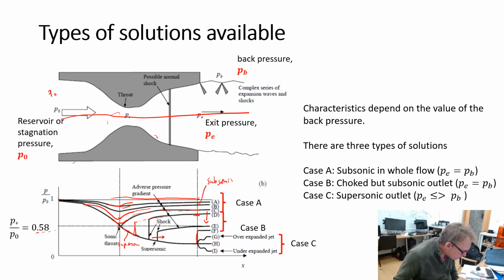Now, what happens, as you see, is that everything collapses onto this kind of unique isentropic flow curve, and the flow and the normalized pressure distribution becomes independent of what you're doing outside and downstream, at the back pressure, providing the back pressure is low enough and the throat is small enough that you'll end up with a choked flow condition.